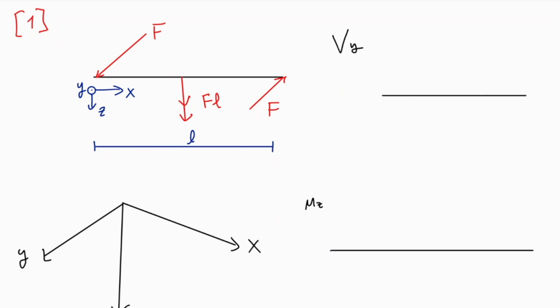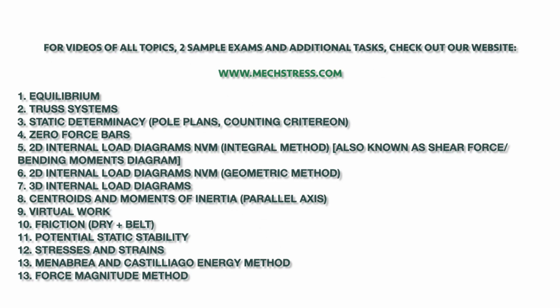3D internal force diagrams are very similar to 2D. We just need to draw 3 additional diagrams for Vy, Mz, and Mx. If you've mastered the 2D case, this should be a very intuitive next step. First, let's discuss how to get Vy. It is exactly the same way that we get Vz in 2D, but in the y direction.